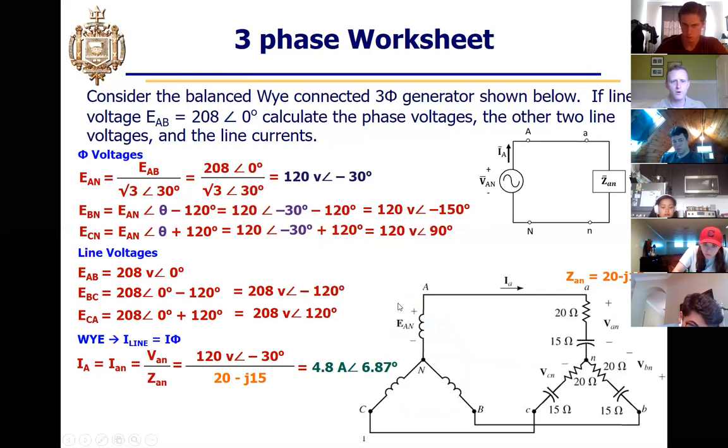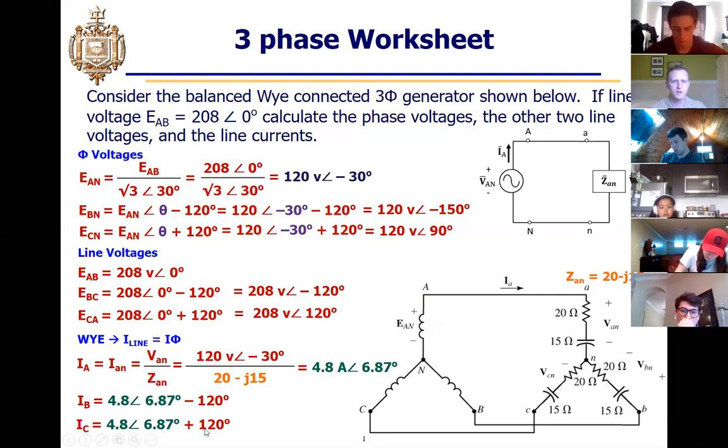The currents are also different phases, and it's shifted by exactly -120, +120. So the math on these is actually super easy. It's just a matter of turning a complicated looking three-phase system into a very easy single phase.